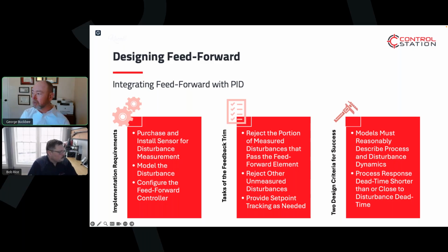And its job also is to manage all the routine accounting of PID control, like keeping in the right mode and handling alarms and notifying the operator and avoiding reset windup, and all of those kind of things that the PID does. It's going to do its thing for the whole combination.